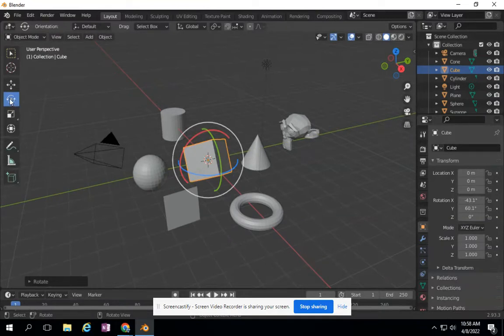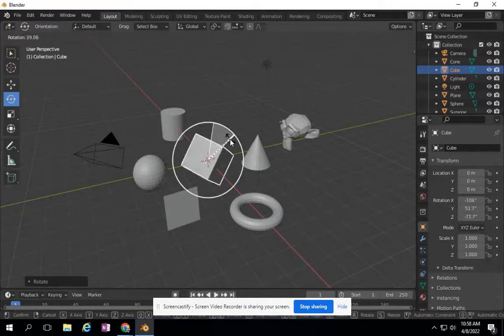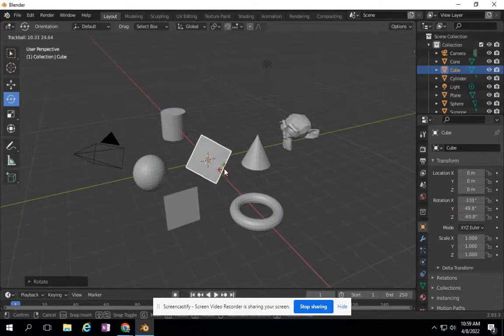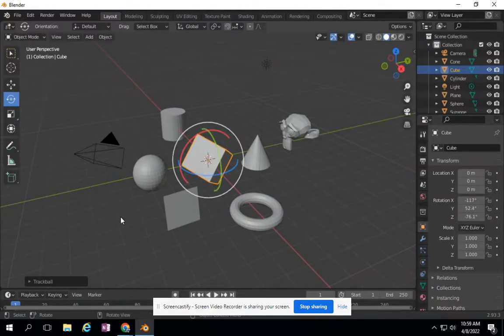Again, that's this gizmo over here. It's called the rotate gizmo. The outside circle kind of does something similar. It just allows me to rotate the object. There's an inside circle that gives me a little bit more free range again. I can kind of spin it in any direction. Very similar to the move tool, just it's rotation. That's the function of it.